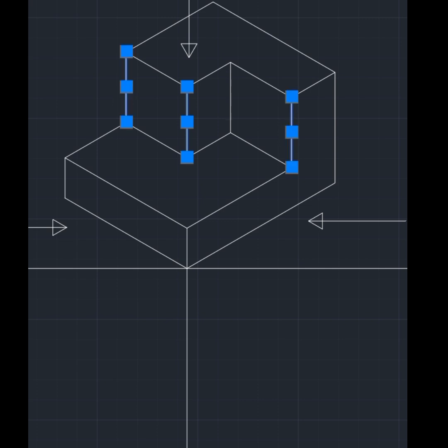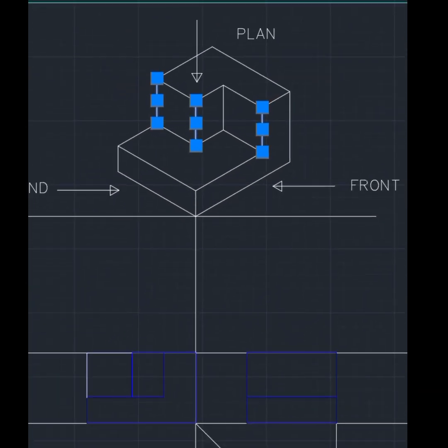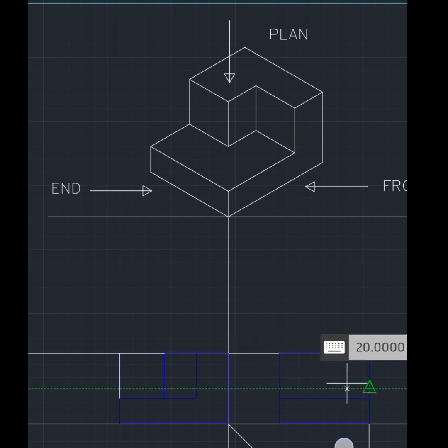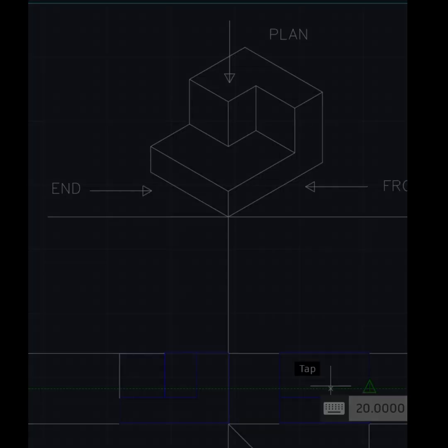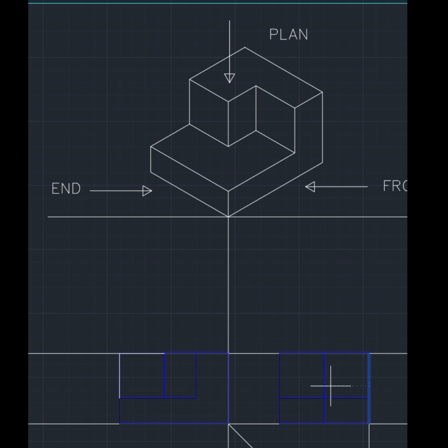So next up, we're going to show this point as we're going to offset vertically. We just finished the horizontal offset. Now this one will offset vertically. We'll divide it into two. It is 35. So we'll click on the line, click on offset, then after clicking offset, we drag our cursor out, input the distance 35 millimeters, click on the blue tick to enter, and that's it.